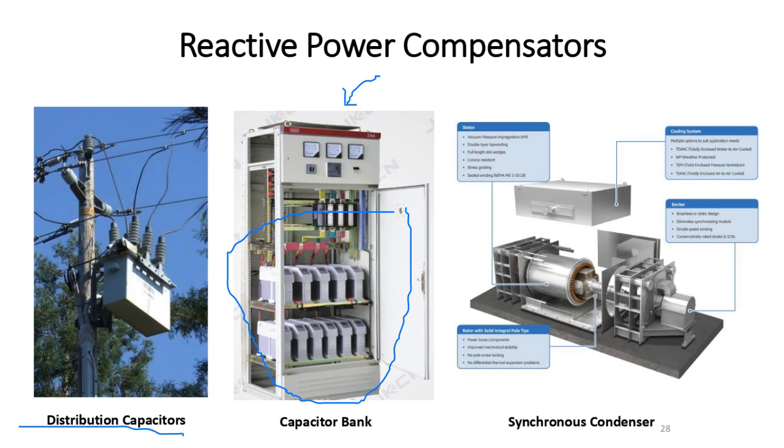It depends how much capacitor we need, and we can control this. If this time we need the whole 60 together, then we take the whole thing. For example, if we want only half, we want to supply only 30, so we only take one part of it. So we can control the capacitors, how much reactive power we need. But if it's a fixed capacitor, then that's it. We call it a fixed capacitor, and it always supplies this reactive power.